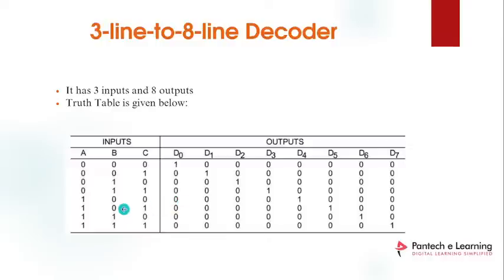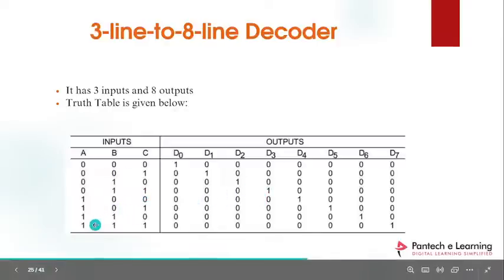These are fixed only. We can't change the BCD because BCD is very crucial and sensitive. If we change the combination of the inputs, we will get wrong outputs. So we have to follow these inputs only. Like if you give 111, you will get an 8-bit output with seven zeros and the last bit 1.